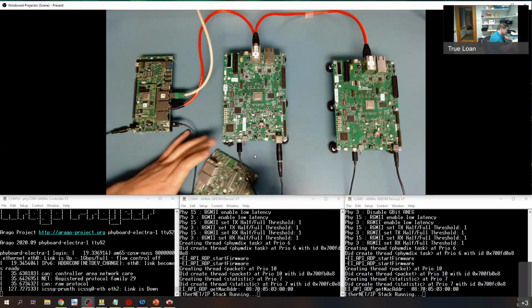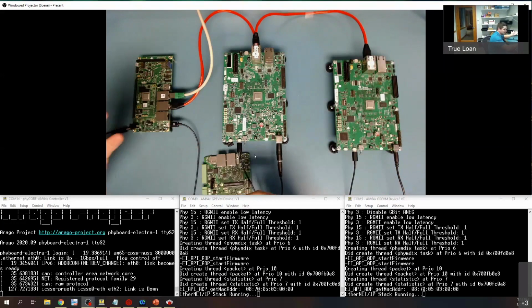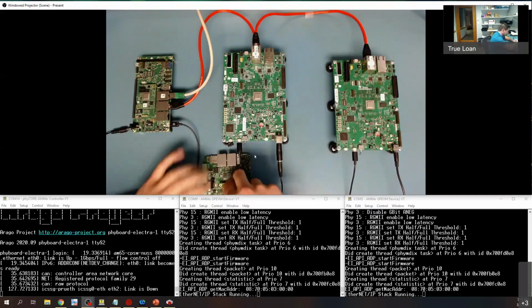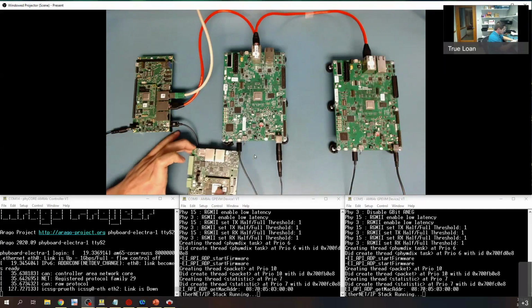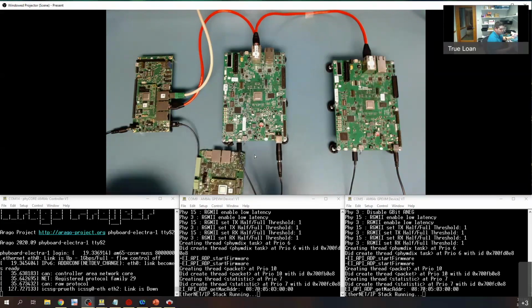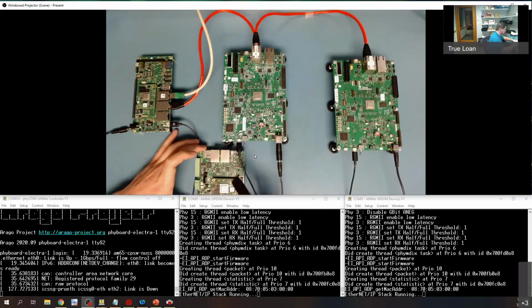Fun fact, this is the board we're going to be utilizing in this demo. We only got them the other night, so we didn't have time to get software ported over to them. But this is as easy as it would be to transition the same SOM. You could have software flash the eMMC on the board, or you could boot from external media like an SD card, and it allows you to very quickly iterate your designs and reduce risk. Rather than respinning a circuit for my flash, customers would be able to just focus on the circuits that matter to their unique application.